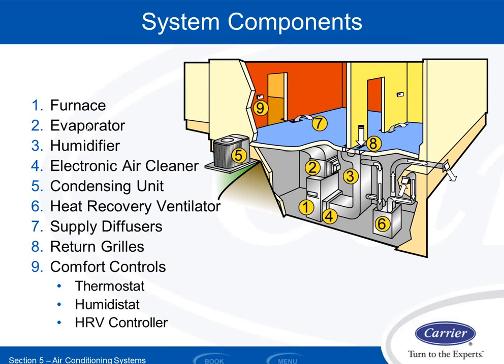But in either case, what that guy's job in life is, I'll see if I can use my little pointer thing here. He takes air from, in this example, it's pulling it out of the return duct, although it's more common to pull it out of the bathrooms and other exhaust sources. We run that air through the ERV, or HRV in this case, and that guy saves the energy from that air.